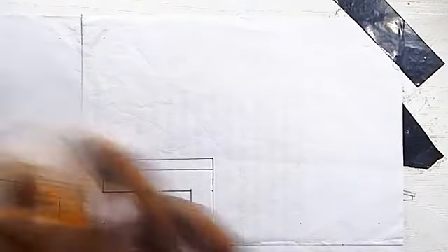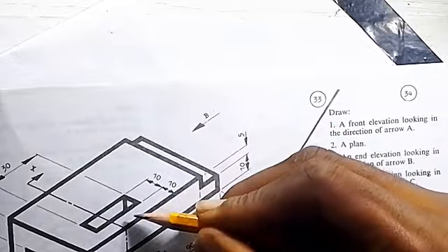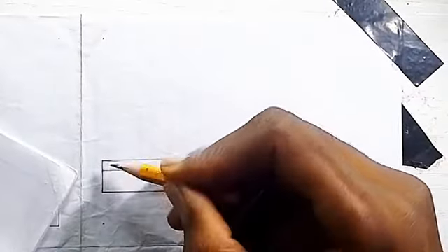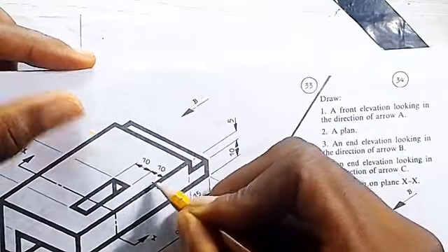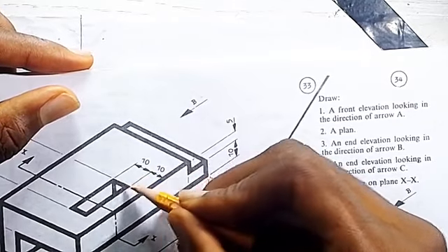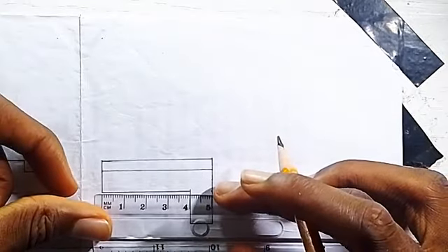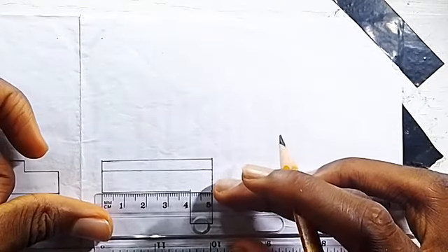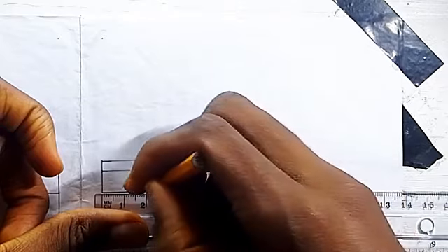So take note, the hidden detail is looking at the end, at this part here, not far away from this left side, which is this left side here. Good, so it is from this left side to the hole is 1 cm distance, as you can see. Then the hole is also 1 cm width. So let's draw that. Keep a distance of 1 cm, then draw 1 cm. So this is it here.